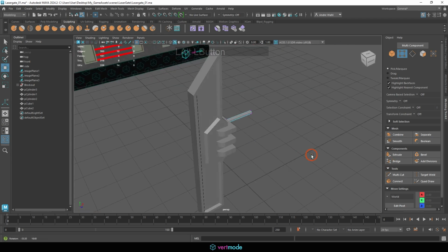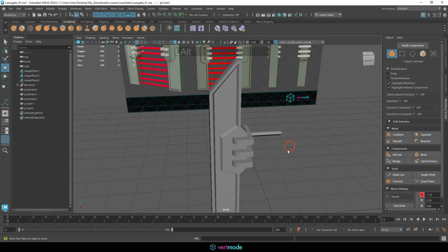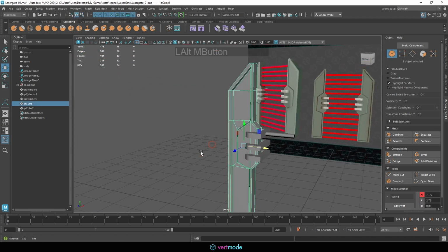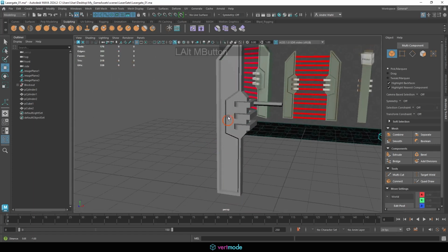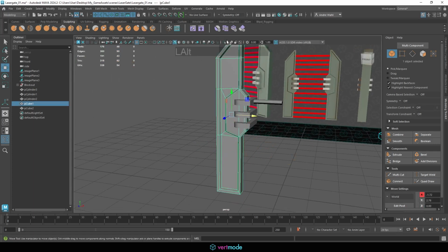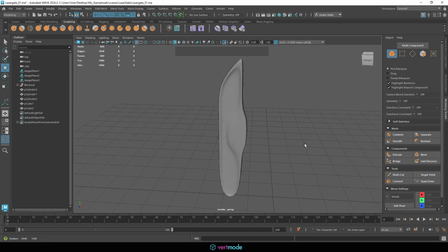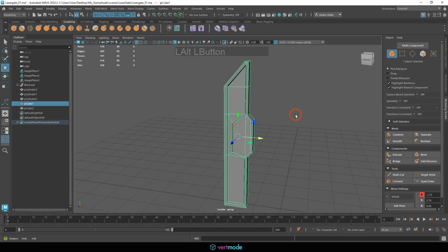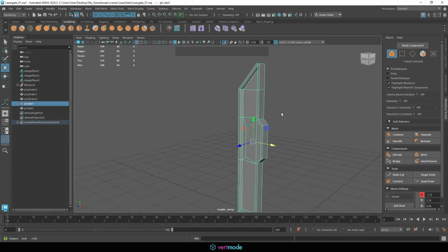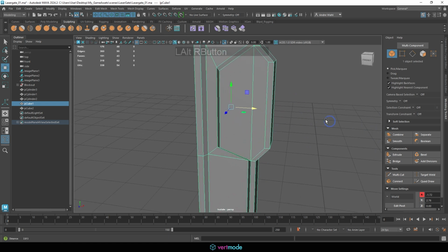Now, the next thing we would want to do to this is add in some micro bevels, so that way it can kind of hold the form in detail. But that's going to be stage 1, is getting to this point. And ultimately, the final stage we want to get to is when we press 3 and smooth this, it all smooths out nicely. So we have a ways to go. But let's go ahead and explore adding in those micro bevels next.